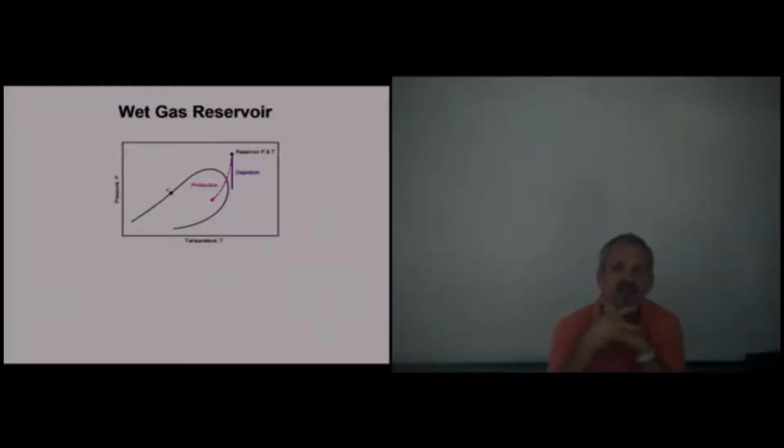So the liquids we're talking about occurred somewhere coming up the wellbore or in one of the separators and never existed as a liquid in the reservoir, ever, ever, ever. I know it's hard to wrap your mind around that, because you look at that liquid in that stock tank and say, how could that have ever been a gas? Only when it was blended with all those other gases and put under pressure and temperature, going in reverse of that dotted line, was it single phase.